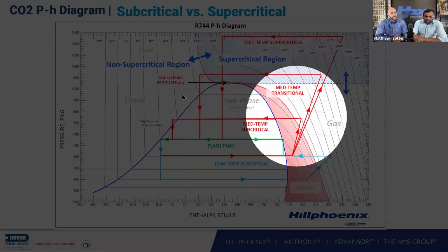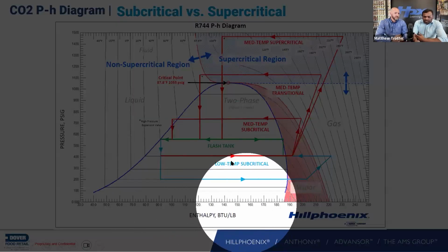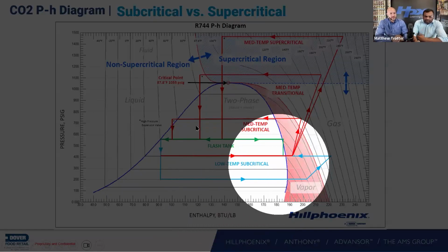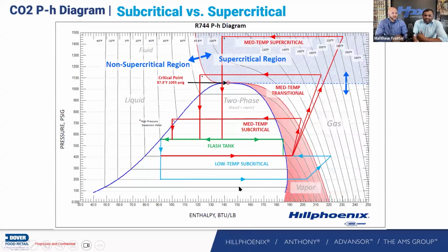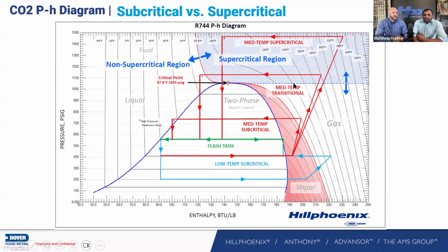So there are 4 different pressures, and looking at what we call the subcritical region, you have a relationship between temperature and pressure. When you increase the temperature, the pressure increases in the subcritical region. In the transcritical and supercritical regions, if you go up here, there is no relationship between the temperature and pressure. So that's different. You can control the temperature separately and the pressure separately. That's a property of the CO2.